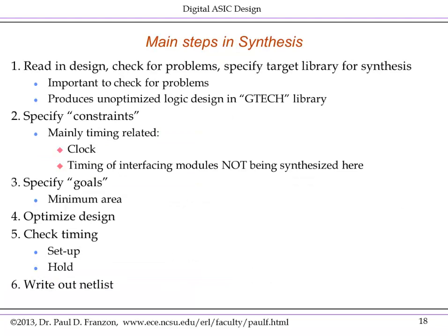So these are the main steps in synthesis. We'll go through the first two of these in this submodule and the last four of them in the next submodule. So the first step is to read in the design, which is more than just a simple parsing of the file. It actually checks for problems, tells you if there are problems that have been identified. And in addition, at the same time, we're going to specify the target library for synthesis.